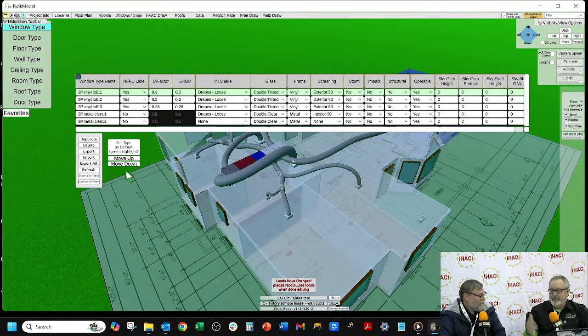I was doing a lot of blower door testing for SMUD, and we tested a house. We didn't realize that an entire window was broken out until we found that. And then we tested another house that actually leaked worse than the house that had the broken window, and we couldn't find a broken window in that house. So it was going somewhere. We had no idea. That's where I walk around, look for doors that come open and stuff. Sometimes attic accesses will be cockeyed, and there'll be a big leak through there too.